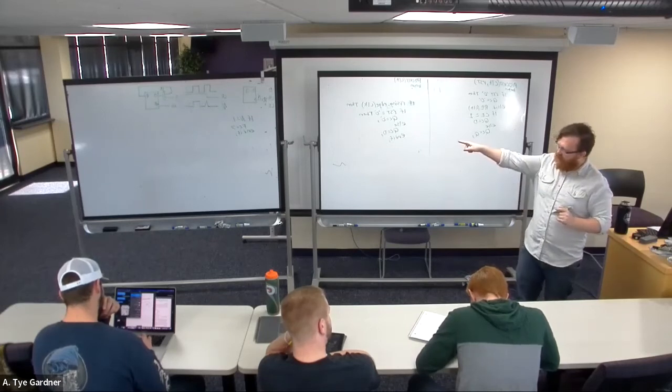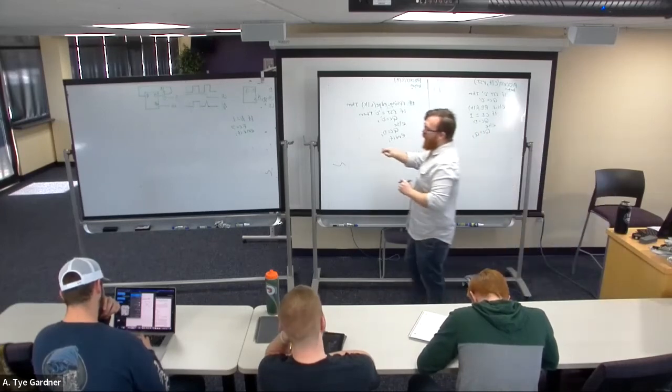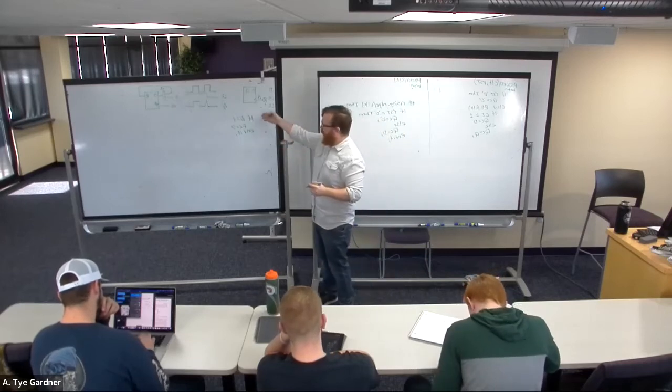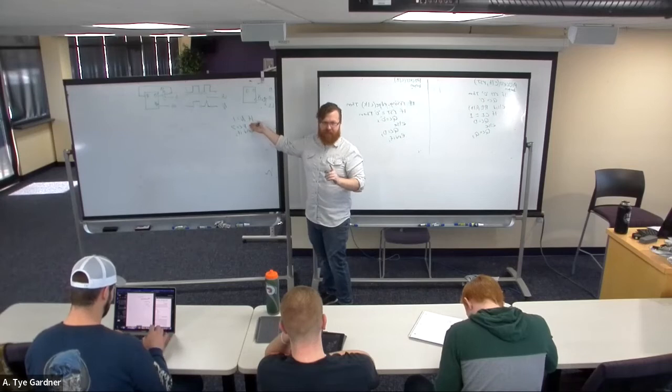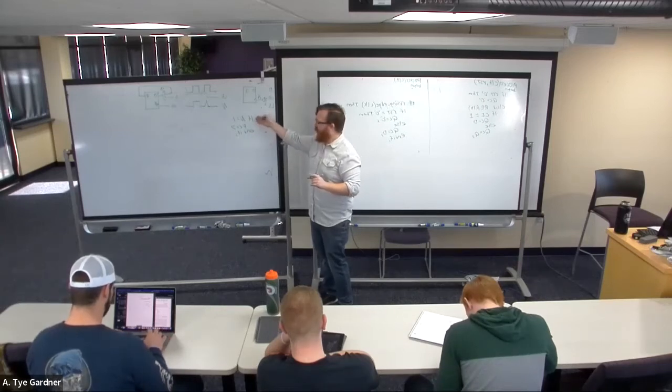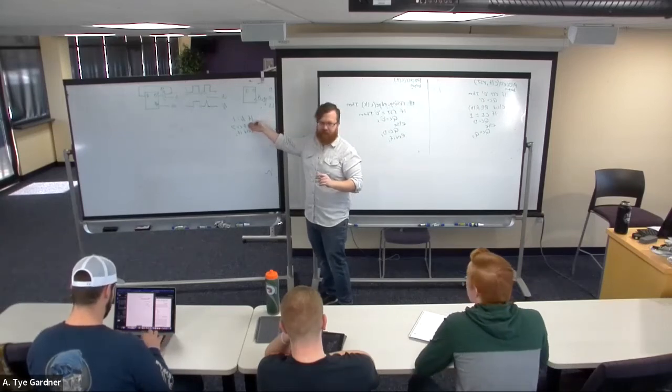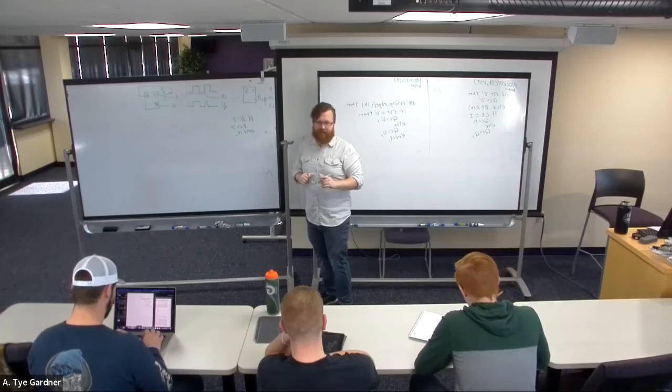What you've said here in Python is if n is 1, update f to 7. In VHDL, in hardware, this says if n is 1, f gets assigned to 7, otherwise I don't care. I don't care what you do with f.